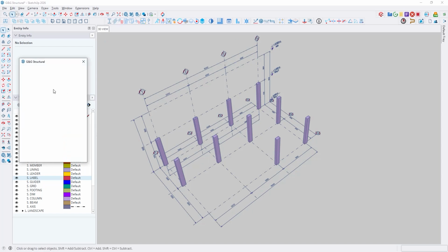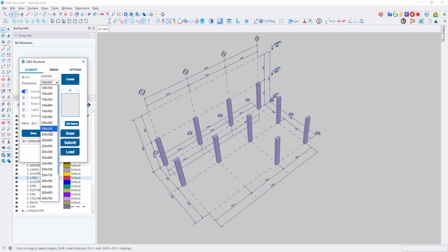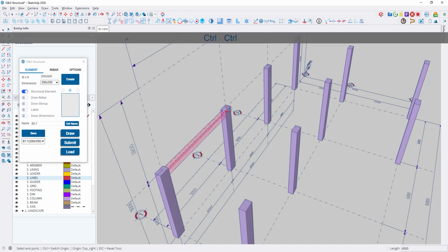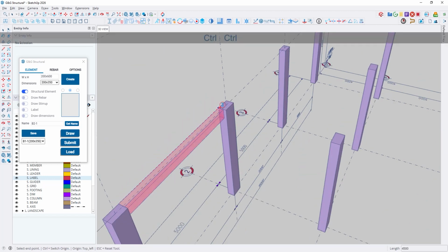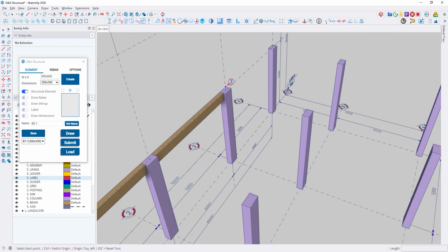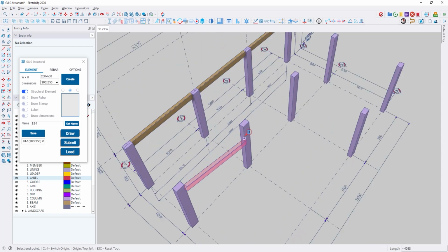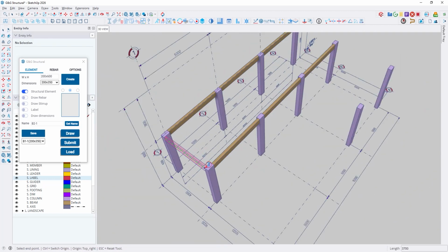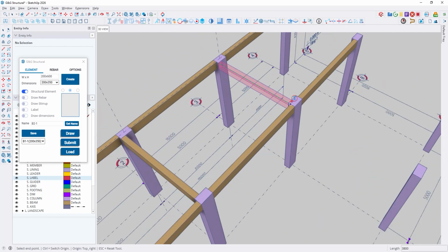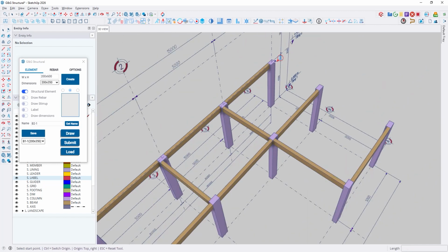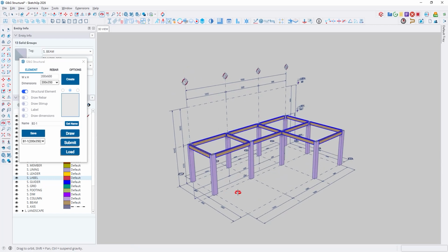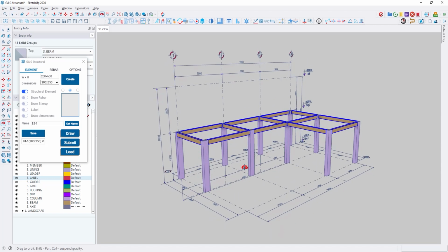Next is the beam drawing module. Users just need to select the beam size and snap the start and end points along the grid or at desired locations. Beams will be automatically created with the correct section, direction, and connection points to the structural system. The plugin supports a fast and accurate snapping mechanism, which is highly optimized for working with structural grids. This makes the modeling process much more convenient, reducing manual tasks and minimizing errors.